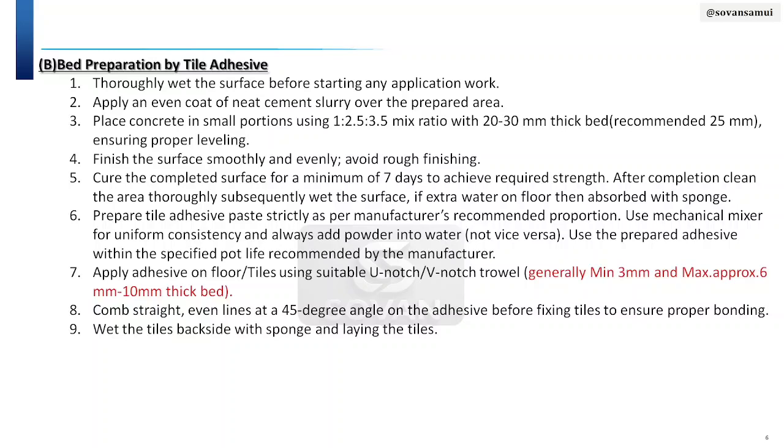Prepare the adhesive within specific pot life. Means manufacturer always recommends the mix should be consumed within a time limit. So you should prepare that quantity of material that you can consume within that time.